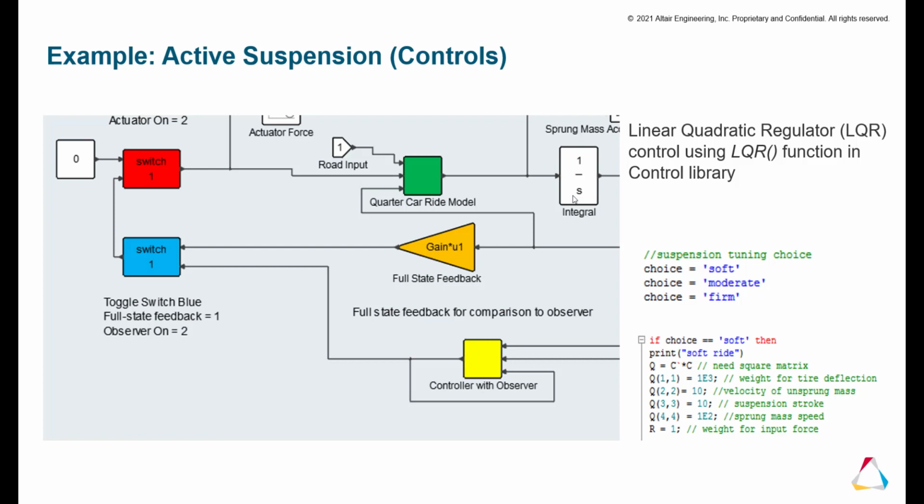And when you're tuning a control system, if you have experience doing so, you know that it takes many iterations, many times running that model in order to measure the response of your system, and then to tune it a bit further, tune your control gains. So you want a model that runs very quickly, and Modelica models run quite quickly, and so do mathematical 0D models as well. So this is a case where the fidelity of the system that you're modeling can have a large impact on your ability to design your control system.